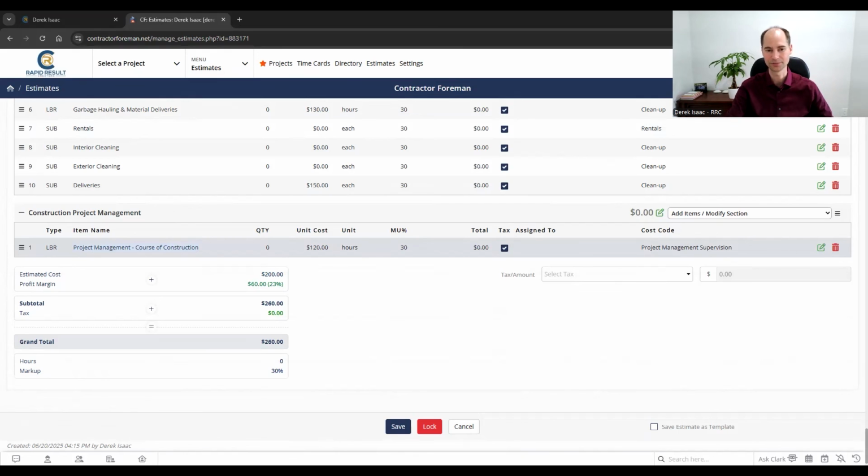How much time is it going to take you to do this project? The good way to figure that out is if you figure you're probably going to spend 1 hour a day or 2 hours a day, then how long is this project? So a new home build takes, let's say, 8 months. With pre-construction, maybe it's longer, but you've got your pre-construction time already. So let's say 8 months, you're going to have 20 working days a month, typically speaking, and you're going to have, let's say, 1.5 hours every day devoted to this project. You can then figure out how many hours, and you top it up a little bit because there's always stuff that comes up. Now you've got an hourly rate and you've got your markup supply. So, very key thing that you need to know here.